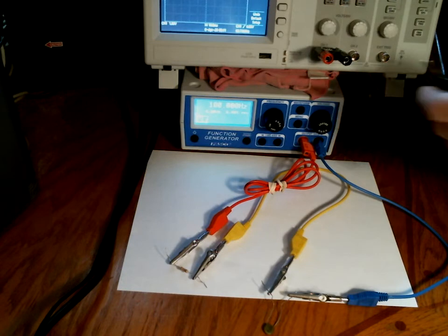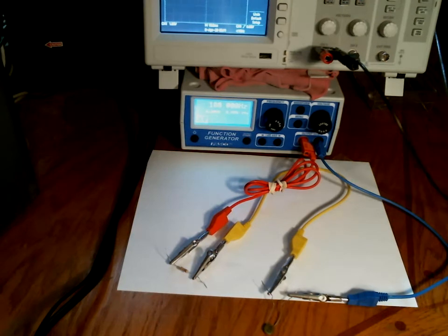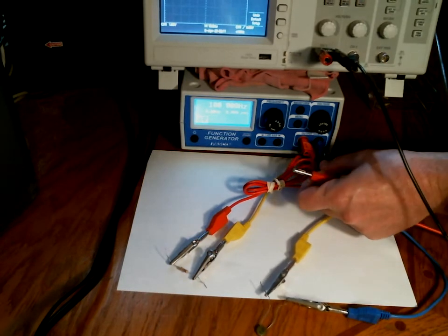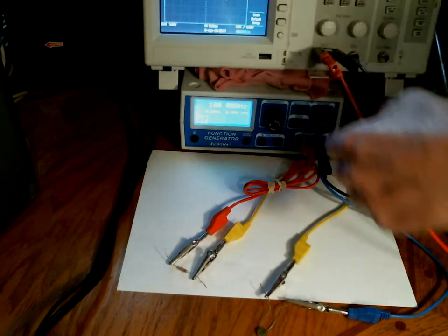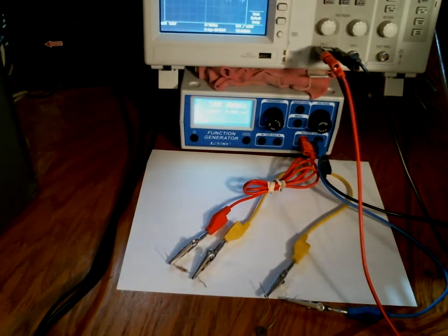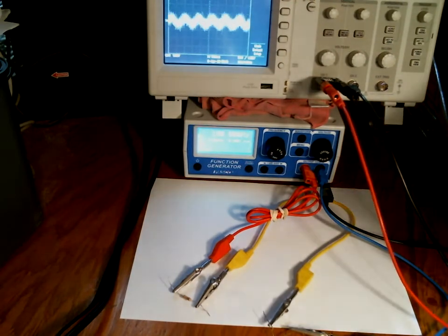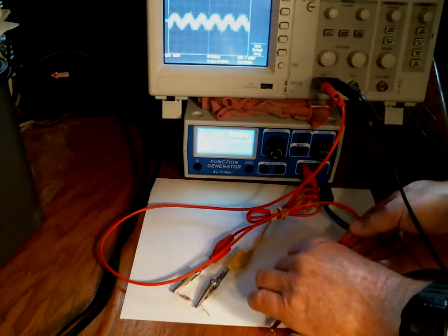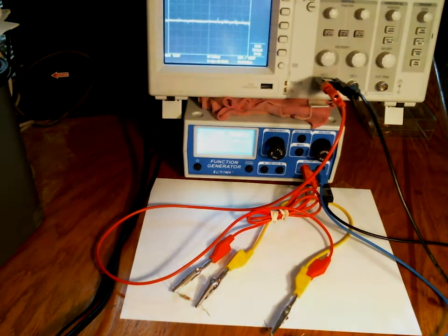So I'm going to go ahead and do that. I'm going to go from the grounded input of the scope straight to the blue wire, which is also grounded. Then I'm going to go from the other input of the scope. Now it's floating and I'm picking up some noise on the oscilloscope. That's probably 60 Hertz AC from the room. And then I'm going to go to the other side of the capacitor. So the oscilloscope, which works as a voltmeter, is now reading the voltage across the capacitor.